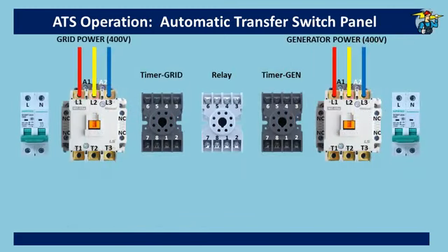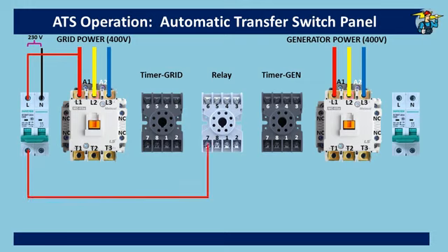Let's take phase line to the grid MCB from L1, and neutral wire also from the grid supply. Control circuit here is single phase 220 volt supply. Relay is powered with the supply from the breaker out, connected to the 7 and 2 ports. From number 7, power line is connected to the common point 8 also.